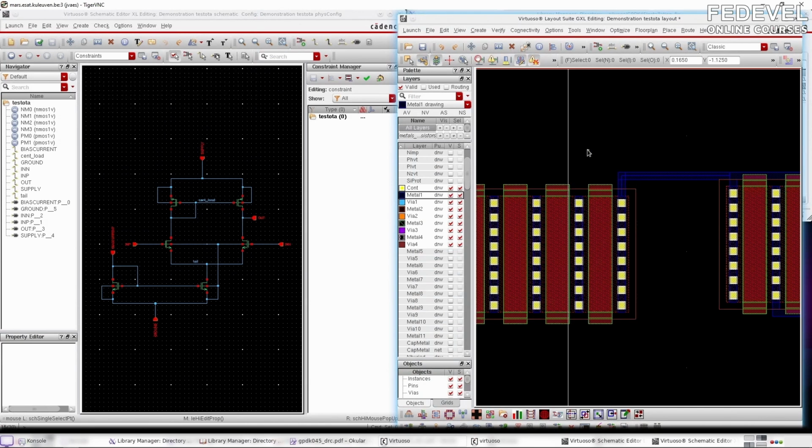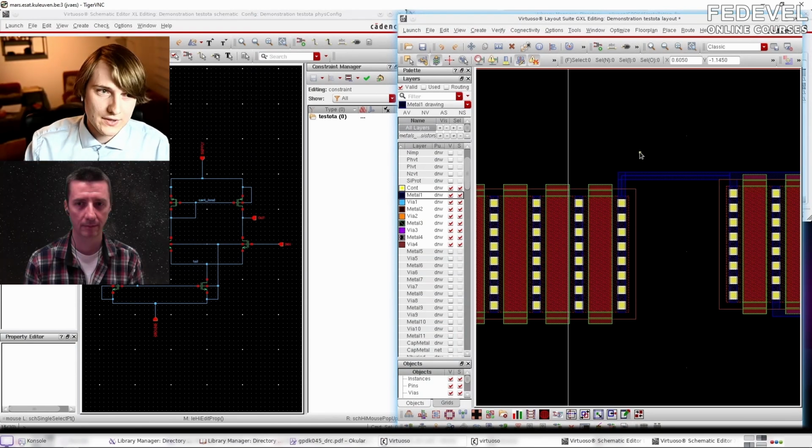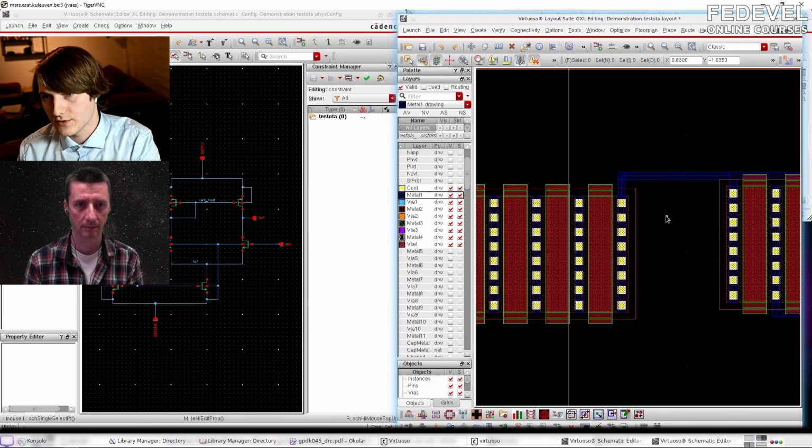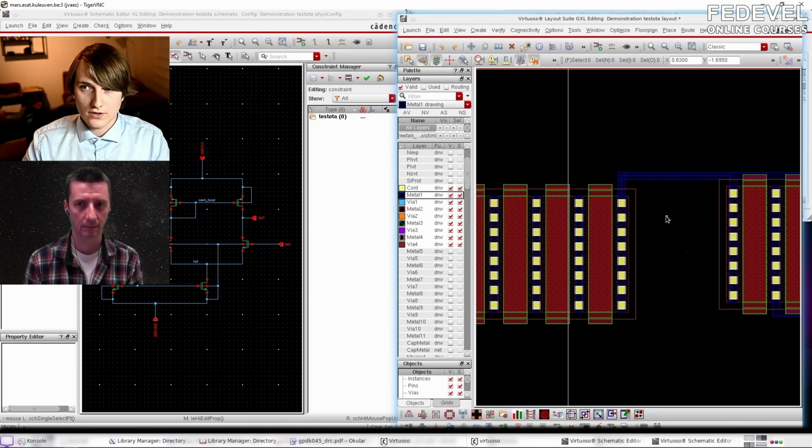What's very important in analog design, and I think also becoming more important in digital design, is that we then need to do a parasitic extraction. We now have all these metals that we've added, and they add little resistances and little capacitances. They will influence our bandwidth and our gain. We need to know how much influence this has, especially if you're going for high-speed design. All of these little capacitances will slow your circuit down and load your outputs. So we do a parasitic extraction.